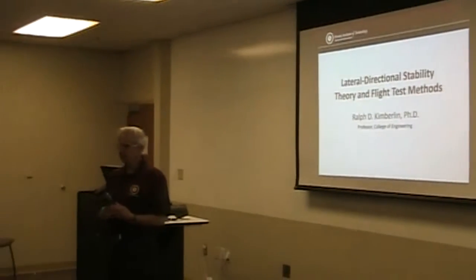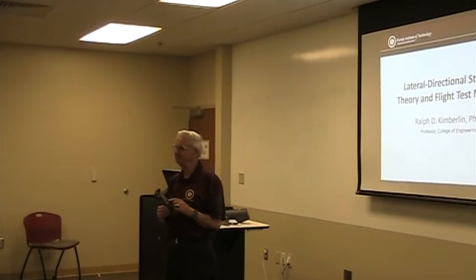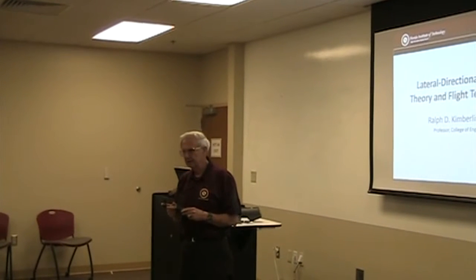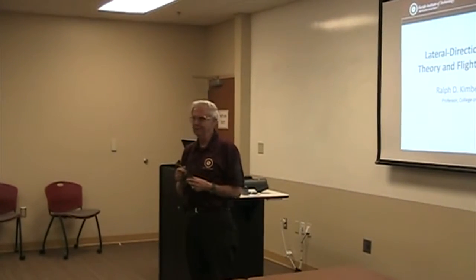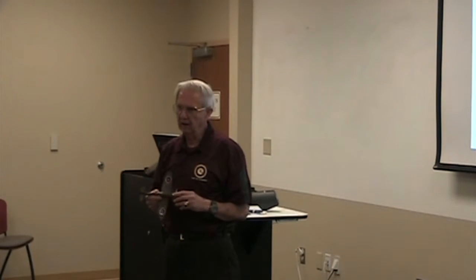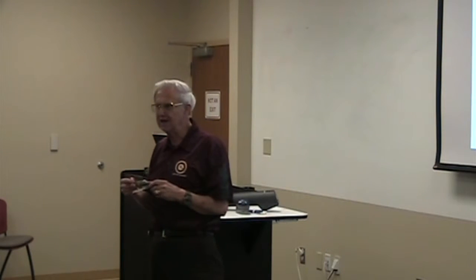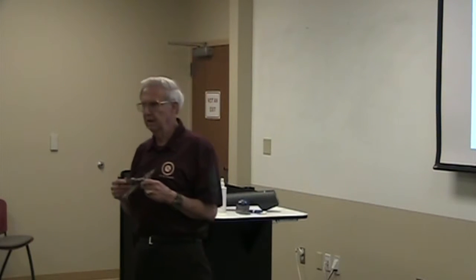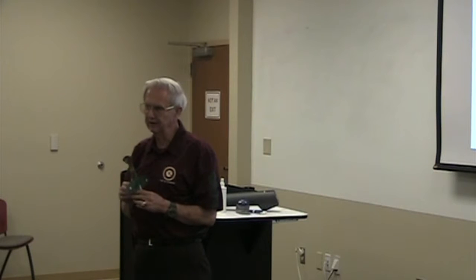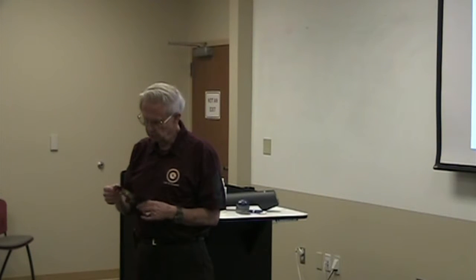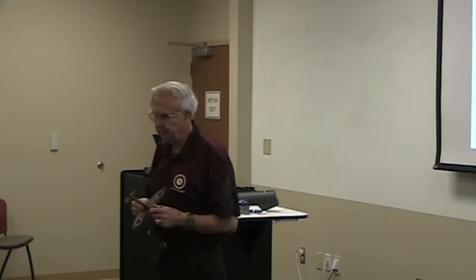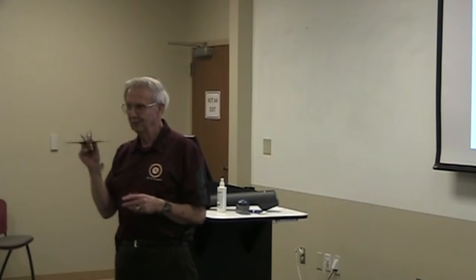We're going to start talking about making the airplane three-dimensional now. And when we do, things start to couple. We get roll with yaw and yaw with roll and those kinds of things. Even at higher angles, we deal primarily with side slip rather than angle of attack. And when we get to rather high angles of side slip, even longitudinal couples a lot of times, and we have some strange motions of the airplane. However, airplanes, unlike helicopters, were made to fly straight.